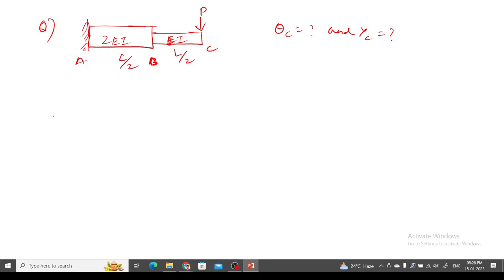So can you please say what the bending moment diagram for this beam will look like? Triangle. Triangle, yes. And what is the bending moment at point A? PL. PL. So whether it should be an upward triangle or a downward triangle? Negative, na? Downward. Yeah, down, negative.